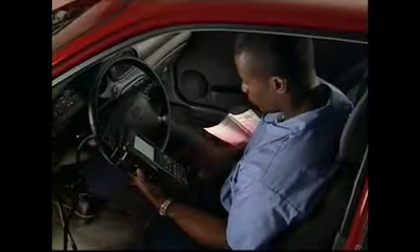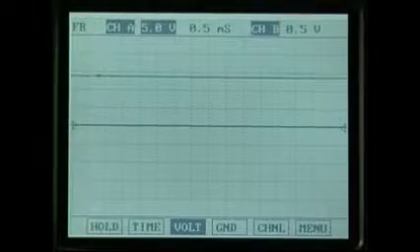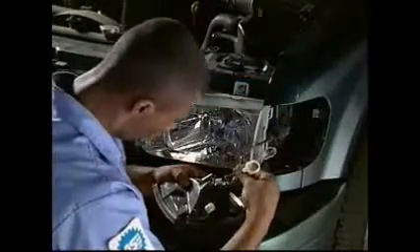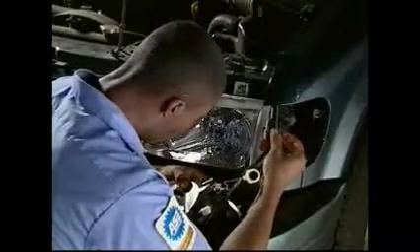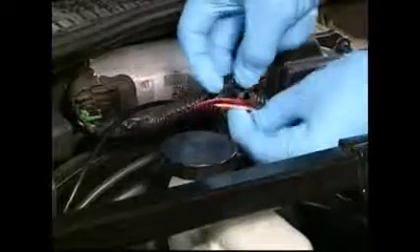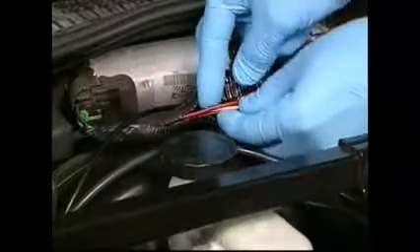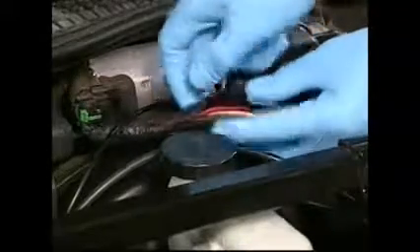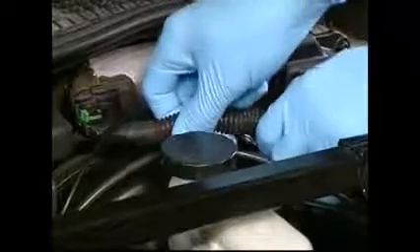So far, we've looked at many effective ways to diagnose and isolate the causes of problems in an electrical circuit. Our diagnosis may lead us to a component, such as a motor or a switch, that can be replaced. More often than not, the problems will lie in the connectors, or in damaged or broken wires or grounds. For a load to operate properly as designed, the wire size used in primary automotive electrical circuits must not only handle the necessary current, but also any vibration and heat exposure.